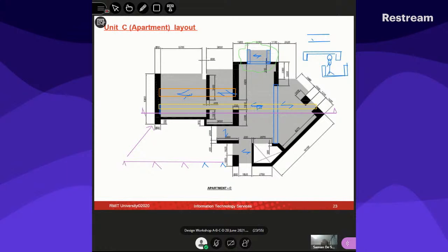The beam has actually turned upside down, and that will provide a balustrade for that particular balcony. And then these beams will extend a little bit towards and have a connection here. So you can do detailing into that. Some reinforcements will be going through the beam, through the slab. Slab thickness can be increased a little bit in that area so that you can accommodate that.